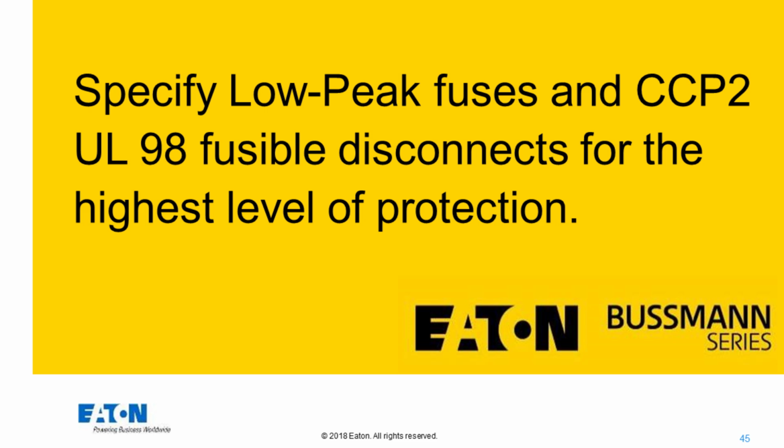Our highest recommendation for motor circuit protection devices is specified Low-Peak fuses, and our compact circuit protection, or UL 98 fusible disconnects, for the highest level of protection. The compact circuit protection is the smallest UL 98 fusible disconnect on the market, a load break device that's motor rated, and the CUBEFuse is the smallest power fuse on the market.